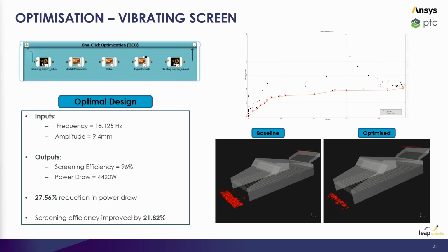So because of this, there's basically one major setting that needs to be tuned, which is the maximum number of design points that it will run. I set this to a max of 80 design points, and for this particular model, it's solved in just about 12 hours, so just an overnight run to find the optimal design based on my parameters and the ranges that I prescribed for them.